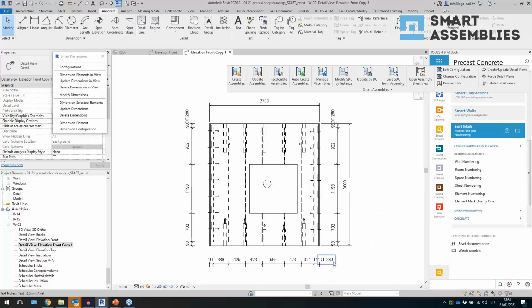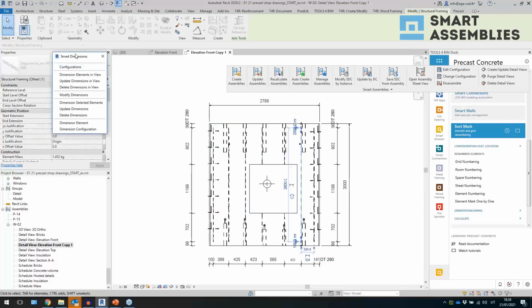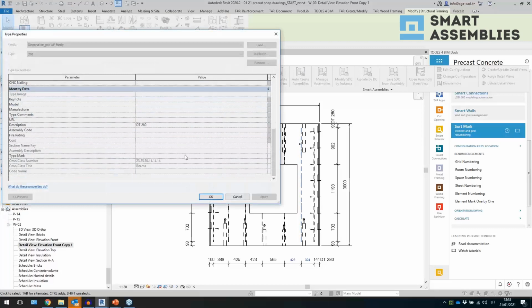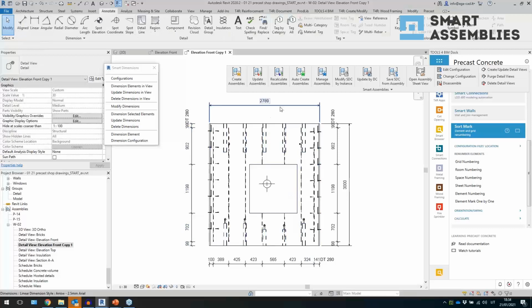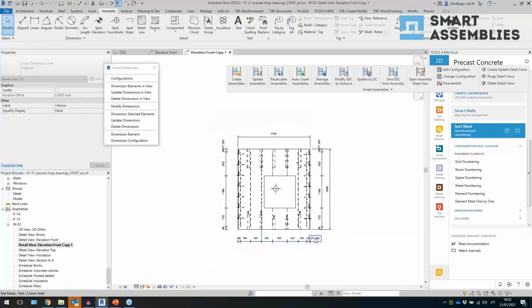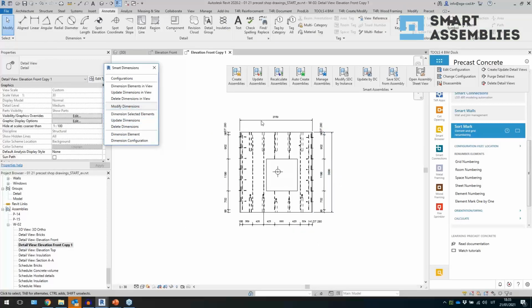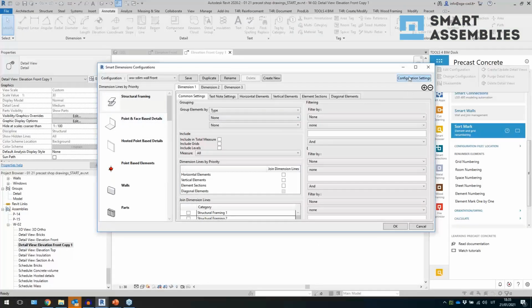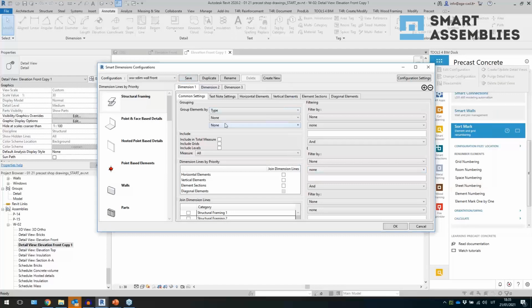All right, so that's what I get here. You see the node gives me the description, which comes from this element, right? If we take a look at the description over here, I have this information in the node. So it could be anything actually. And then, it's just measuring the position of these lines, and the horizontal lines also give me the position of these structural framing elements. I also have this total dimension, but I will remove it. I will use it from Smart Assembly. So here's the total measure position, so I'm just going to remove it. I don't want to use it.